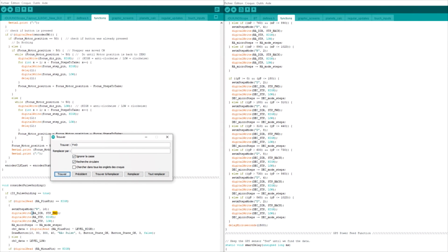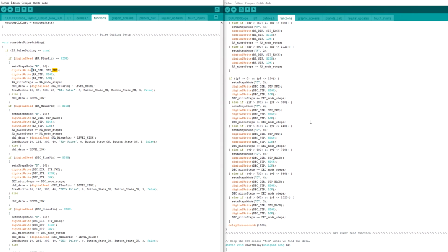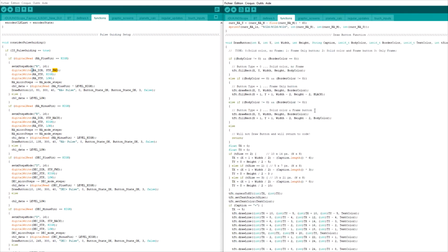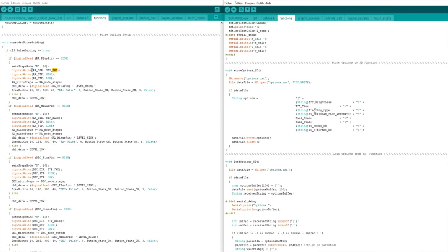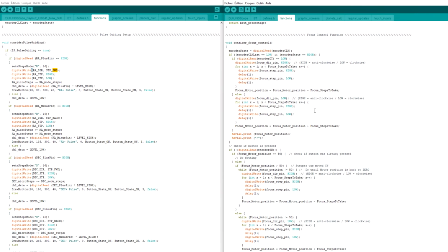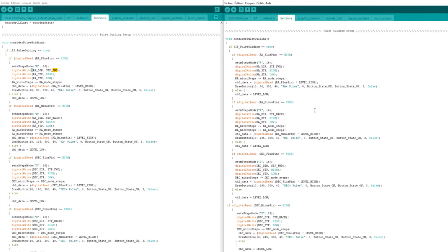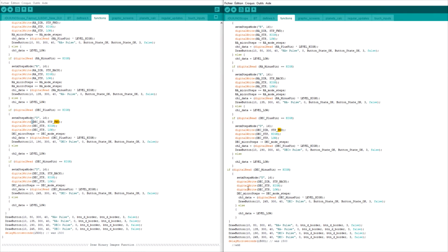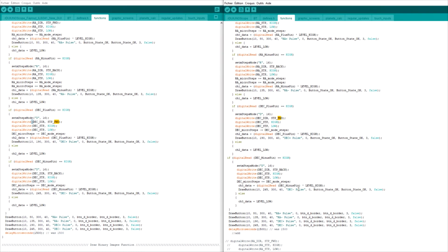Then if we look at the next forward occurrence in the code, we go into the pulse guiding setup, which is the Autoguiding part of the code, and here I hadn't changed anything in these strings because when I did all this modification to invert the spinning way of these motors, I hadn't tested the Autoguiding mode. But now it is working, and I had probably inverted some wires in the Arduino Nano board, and then as I said, the Autoguiding mode is working, and I don't modify this code now because I don't want to alter the Autoguiding behavior.